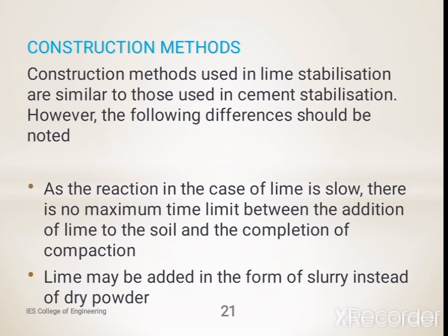Construction methods used in lime stabilization are similar to those used in cement stabilization, but there are some differences. They are: as the reaction in the case of lime is slow, there is no maximum time limit between the addition of lime to the soil and the completion of compaction.